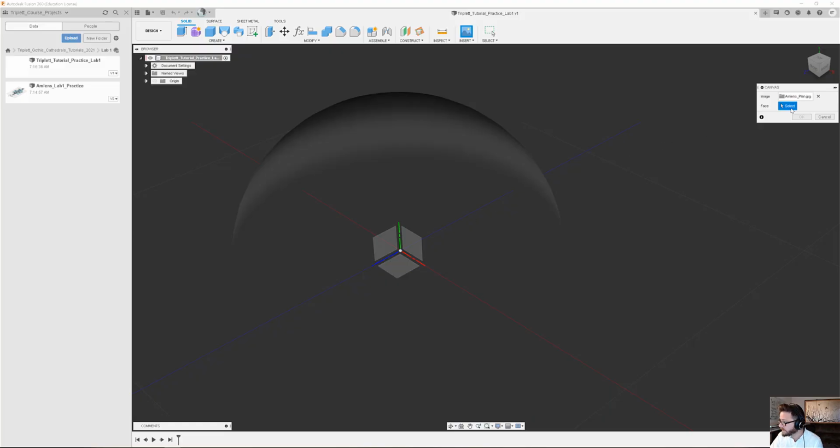So the first thing it's asking you to do is select a face on which to put your canvas. Okay, so we hit Insert Canvas, and then it says Face. And what we want to do is put it on the bottom face. So if we see this view cube at the top right-hand corner, we can hit top like this, and that will at least remind us what direction everything is facing. Right now you're seeing that top is spelled sort of sideways. So what I want to do is just quickly turn this over so that the top is facing the right way. That just keeps me oriented. It's just an easy thing to do.